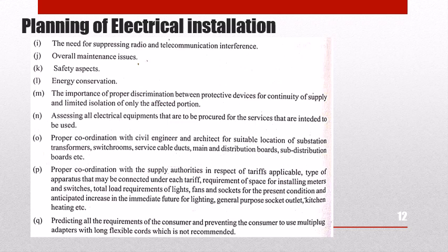affected portions, and also assessing all the electrical equipment that is to be procured for the service that is intended to be used, and proper coordination with the civil engineers and architect for the suitable location of the substations, transformers, switch rooms, service cable ducts, main and distribution boards, and sub distribution boards.